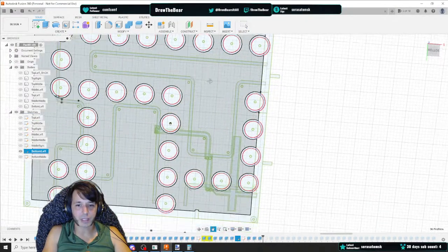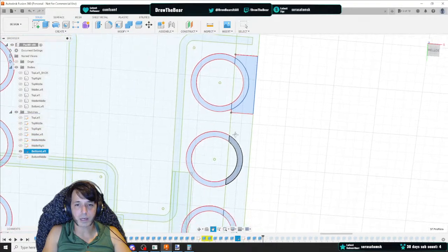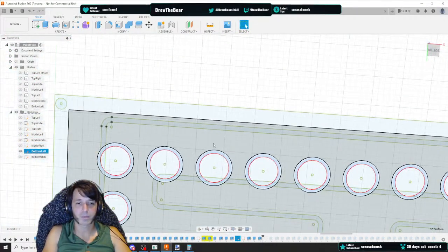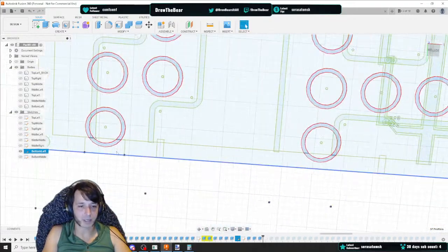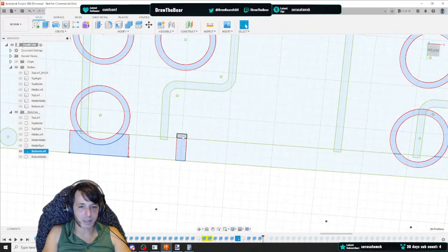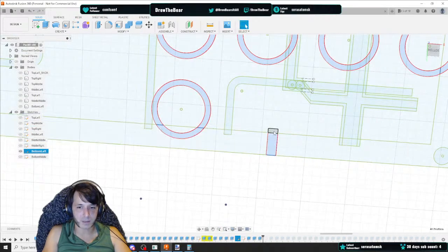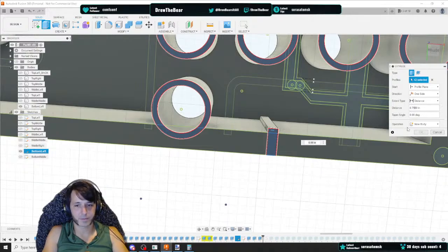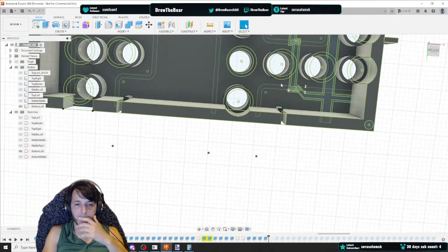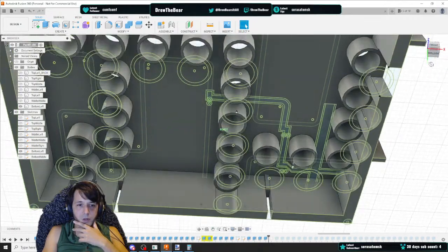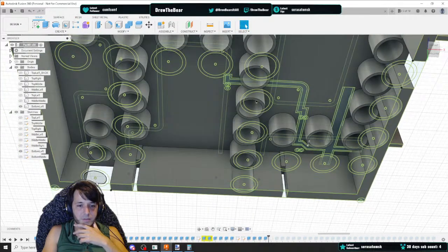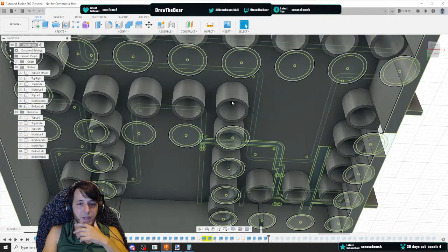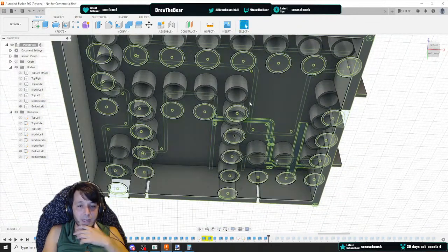And then I need to do the, oh, it's upside down. So yeah, it's down here. Okay. That, and then the connector sockets. And we're going to extrude all of these to 0.75. Okay, so now, if you look, the holes are a lot shorter. There's a piece right here. There's a socket for these other rods to line up with from the other pieces. And it's looking pretty good.